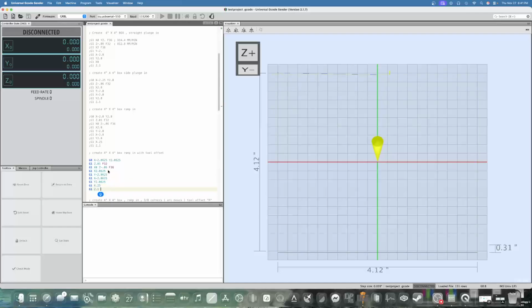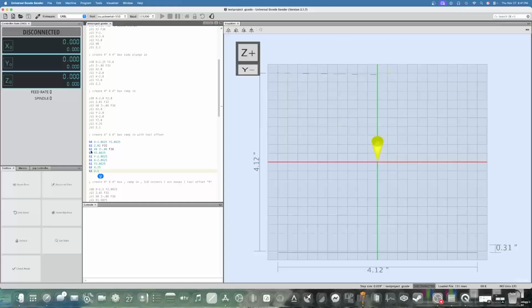And that's all pretty much the same as before. And just straight lines. As long as it's G1, you're feeding into the part. We can do G0, but that's a rapid. G1, and you tell the coordinate, like if you come over here 1 inch and Y 1 inch, that's 45 degrees, 1 to 1. And if you're starting at 0, it would draw a 45-degree line straight up to that point. I do recommend you get UGS, put it on there, and start playing with it, and you'll see. Now, as you notice, the visualizer doesn't update as soon as you make a change. You have to come up here, click File, click Save, and then the visualizer will show it.